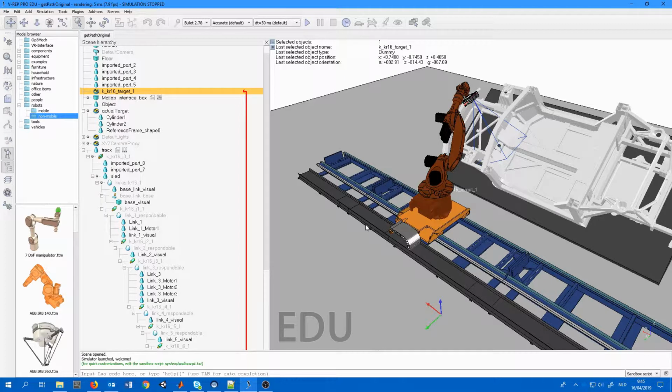So let's now start by implementing the features that we need. Maybe I shall list them first. What we want is to move the sled or the track separately from the robot. Why do we want this? Because we don't want this to move too much. If you do this like this, and inverse kinematics can change this position, it will change this too much actually for a good trajectory. So that's why we want to do them separately.